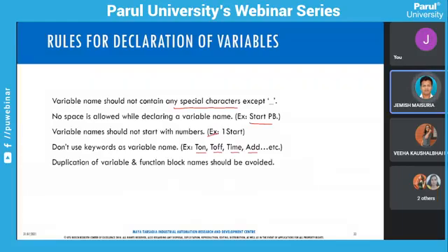that will depend on the software which comes with that particular PLC. If you take a PLC of Allen Bradley, then Rockwell Automation will provide the programming software, that is nothing but CCW, Connected Components Workbench. So you require that software, and through that software you can do programming of the PLC. If you have this particular Bosch Rexroth PLC, then you require IndraWorks Logic as software to program that PLC. So different makers will have different kinds of software, but they all follow DIN ISO standards. So that DIN ISO standard is nothing but what?